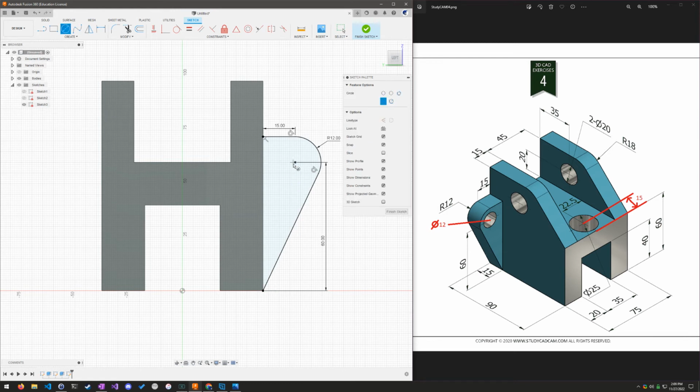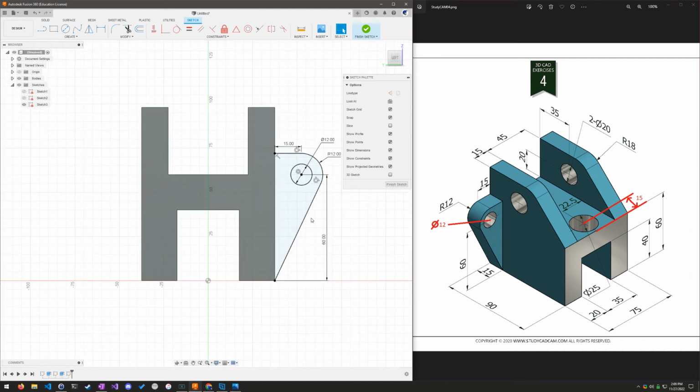Now we've done holes a lot, so we're just going to go ahead and make this hole here, since it's fairly simple. We're just going to make this along with our extrude to save us some steps. So this is going to be 12, and I believe that's it. So now we can mirror this whole thing. So I'm going to turn the origin eyeball on so I have access to that Z line, because that's going to be where I mirror from.